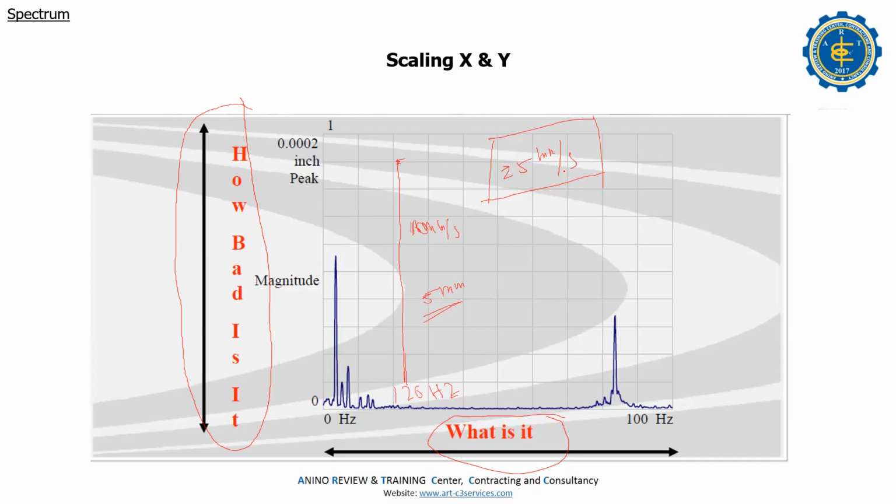That will happen also in our fans in Saudi Arabia. We also get 25, 30 in the fans. But we only shut down if the bearing is damaged. If the bearing is not yet damaged, we will not shut down, because at 30 mm per second, maybe only after 1 to 2 hours, it will go down. But if the vibration will not go down and keeps increasing, that's the time we will check the bearing. So that's why we have to monitor how many times I monitor the fan.